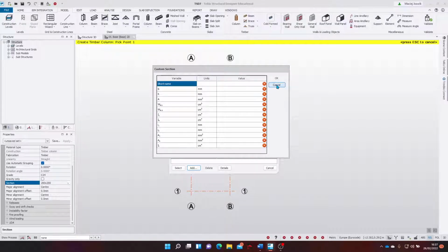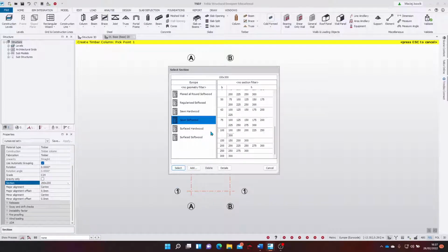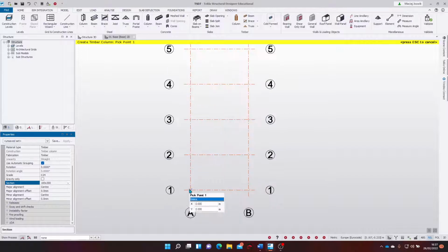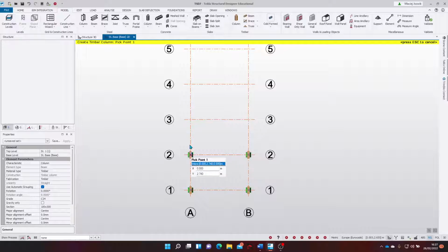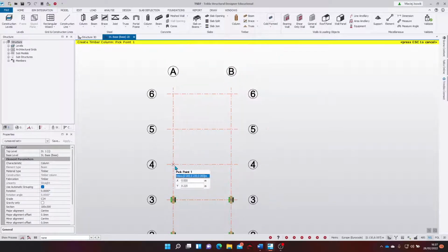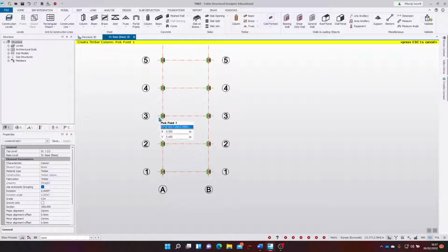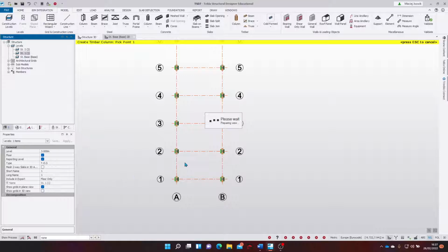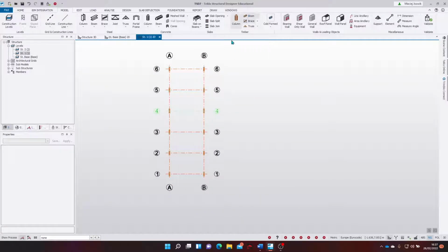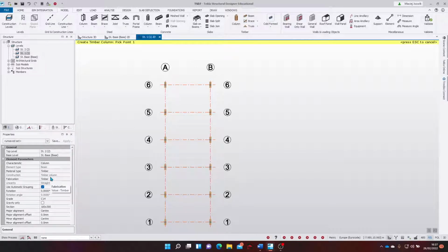Essentially, I would be careful if I were you. Right, 100 by 300, select, and just like in Revit, we'll introduce columns at the intersections of vertical and horizontal grid lines. Now let's go to level 1 view and create the 90 by 90 columns here.